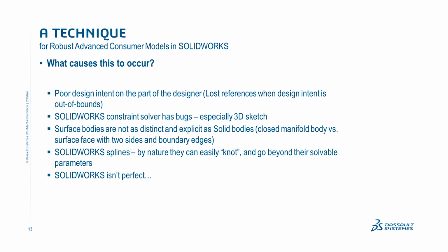And that's why solid modeling and SolidWorks work so well, because they're manifold closed shapes and they're well understood, and there's less variables than there are in surface modeling. Another part of the problem is that in creating advanced shapes, we by nature also create the underlying curves that create those shapes. And those curves oftentimes are defined by splines, both 2D and 3D.